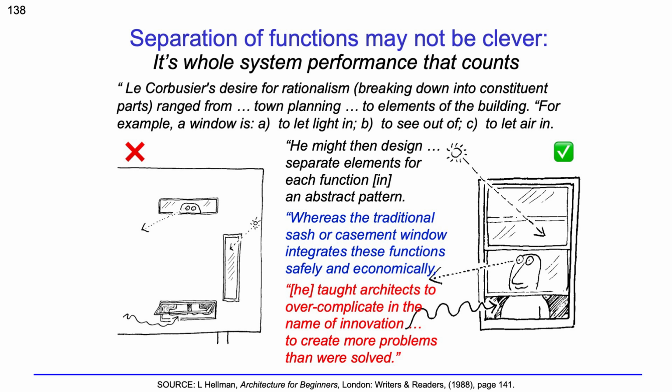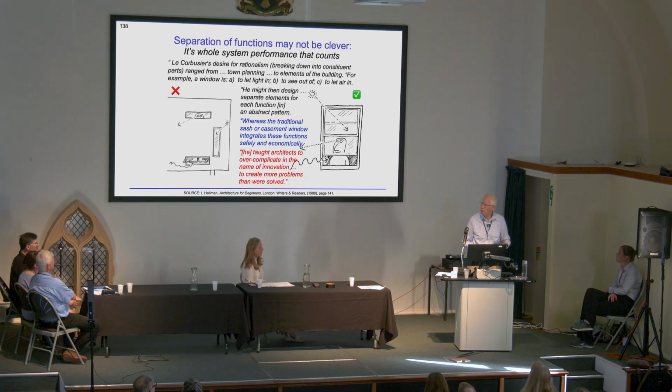But in general, windows that are replaced or in modern buildings often lack the functionality of the sash. And it's also a problem. The sash stays in the plane. You have curtains inside, you can have secondary glazing inside, you can have shutters outside, you can do what you like, and they don't bang into each other. I mean, one modern building I looked at in the 90s, the external blinds which it had were a guillotine for the openable window.